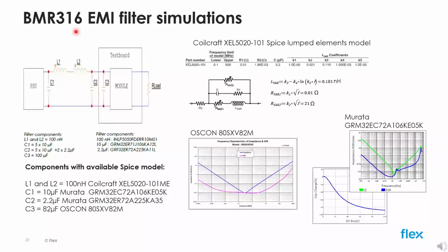It uses a resonant LLC topology switching at 1 megahertz, and it's typically used in data center computing boards using 2 steps power conversion. Its natural output load is a 12 volts in voltage regulator module supplying high power GPUs or large system on chips for AI. You can see the list of filter components under the schematic.